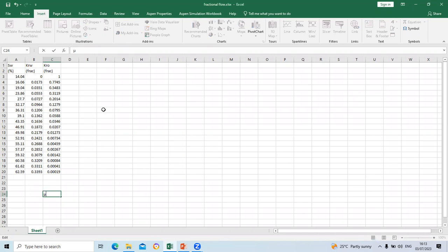Insert, all right, close. Viscosity of oil, let's put our 0 there, is equal to, let's say, 0.9. Remember, I said water flowing activity goes for very light oil. It cannot go for heavy oil, because if the oil is heavy, the most appropriate technique is to apply maybe steam injection, so that the steam will go and break the long chain hydrocarbons into smaller chain hydrocarbons and make it lighter.